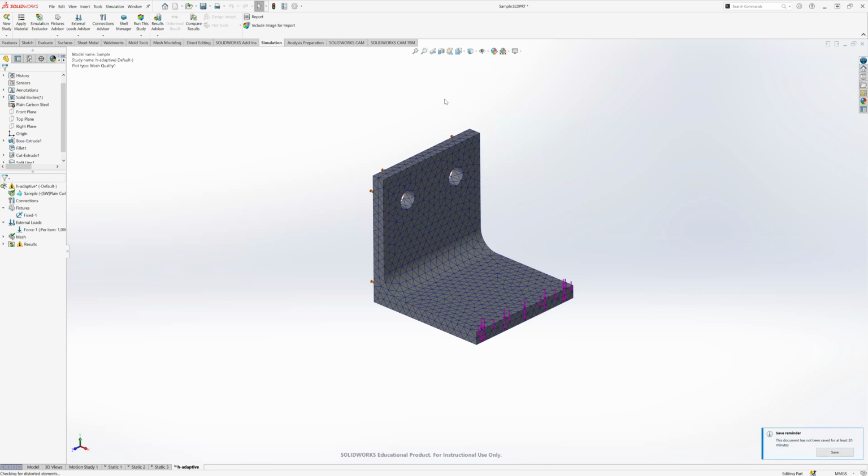Before I actually run it, you'll see it run every iteration. Once you come up here and start seeing your stress pop up, it'll keep running, and after every iteration it'll display the stress. Depending how quick they run, sometimes it's fairly quick, but you can get a general idea of how your stress is differing between iterations or loops. So what I'll do here is right click, run.